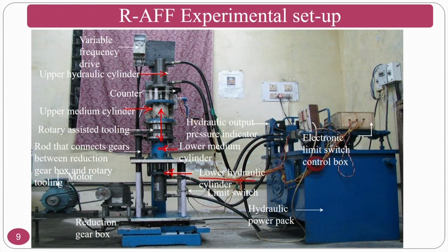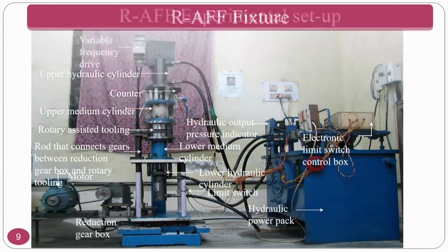The motor drives the reduction gearbox. There is a high gear reduction ratio, from where these are connected, and from here this is another gear which is enormously reduced, and this imparts motion to this particular gear, and similarly this is connected here, and this is imparted to the workpiece. Okay. That is how the rotational motion is given, and anyhow you have the hydraulic power pack to give the reciprocation motion using hydraulic energy.